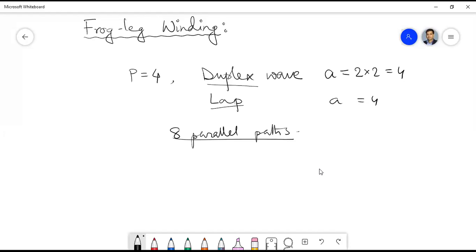Why winding? Because if you are using copper coil in the rest of the slots, you have to use the copper winding there, because that copper only will have the same weight. Otherwise, it will create some mechanical imbalance. Though it will not take part in the armature current carrying, it will take part in the mechanical balancing. So that type of coil is called the dummy coil.